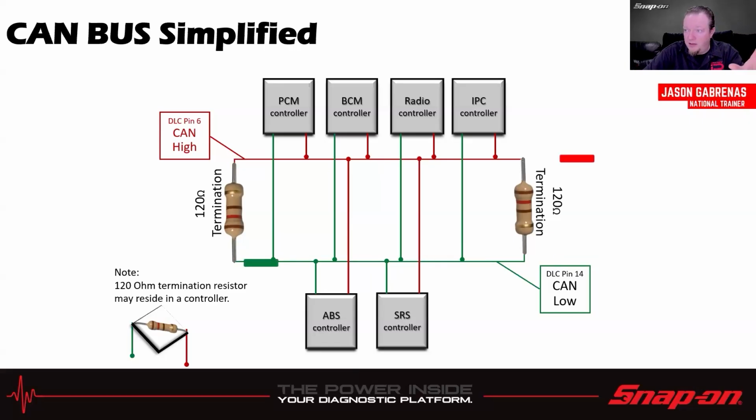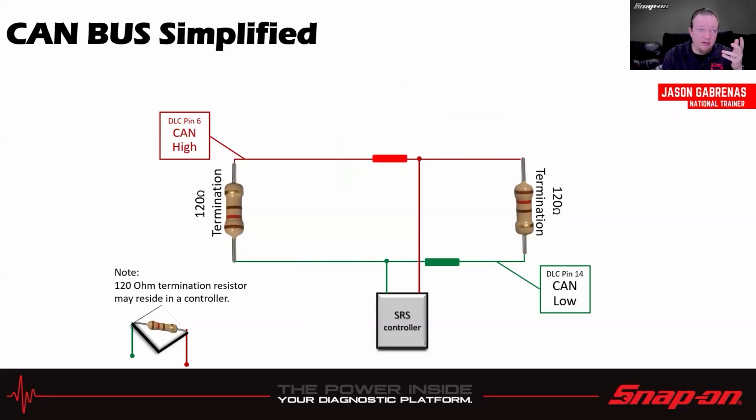So they decided to branch off into multiple buses, and there are a couple of different ways they could do it. They could either terminate the buses at the OBD2 port, or they can have it go through a gateway module, which would separate it out. And we'll talk about gateway modules here in a little bit. Or other ways that we might see a little bit later, like breakout blocks and termination blocks. And also, we can remove all the modules but one, and then one module will talk. Because guess what happens when you hook a scan tool up to a network? It becomes another module on that network.